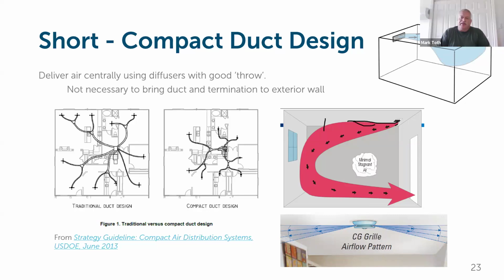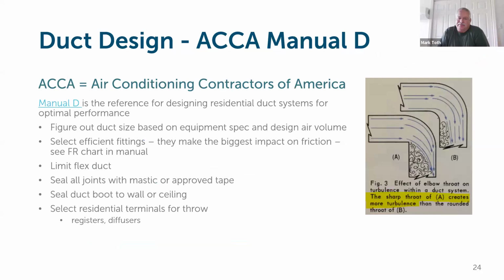Well, that brings up the point. There are some units I hear of once in a while. I think Panasonic makes an ERV or an HRV that is just one piece that goes in the bathroom. It looks like a bathroom fan, and literally, I mean, their equipment's their equipment. If they're selling it, that's great. But in my view, the air comes in and goes right back out. It can't disperse because it's pulling out at the same place as it's putting in. So it's going to short cycle air through the room in that case. Yeah, good things to consider.